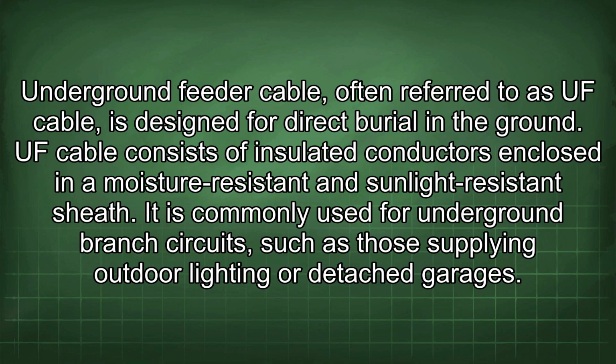Underground feeder cable, often referred to as UF cable, is designed for direct burial in the ground. UF cable consists of insulated conductors enclosed in a moisture-resistant and sunlight-resistant sheath. It is commonly used for underground branch circuits such as those supplying outdoor lighting or detached garages.